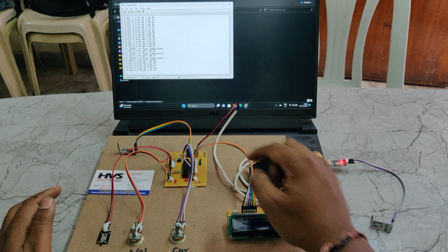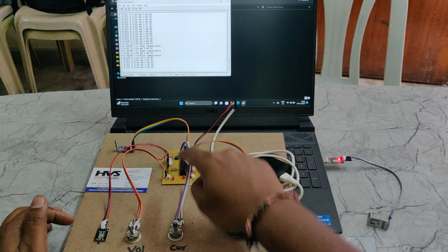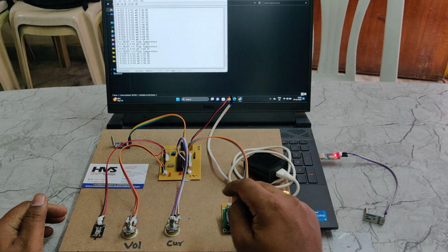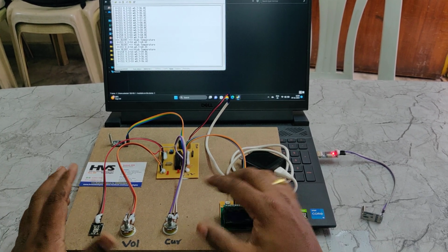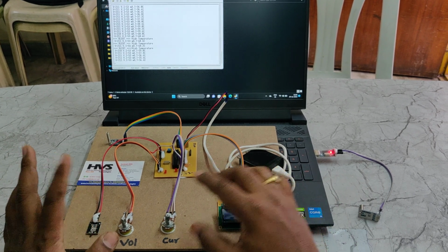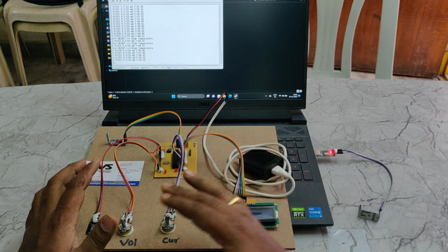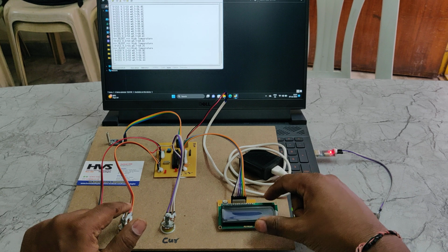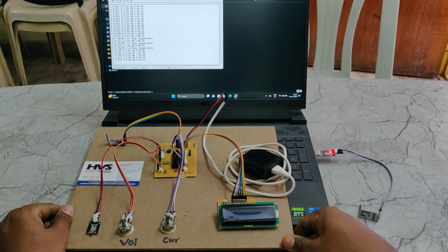On this motherboard, this one is the reset switch to restart the microcontroller, and this steel plated one is a crystal oscillator, which is used to provide the clock pulse to the microcontroller. The purpose of the crystal oscillator is that we have provided a set of instructions to the microcontroller for reading input, controlling the output and sending data to the wireless communication. These instructions need to be executed based on the clock pulse for the microcontroller. Each pulse will execute each instruction. So let us see the demonstration.